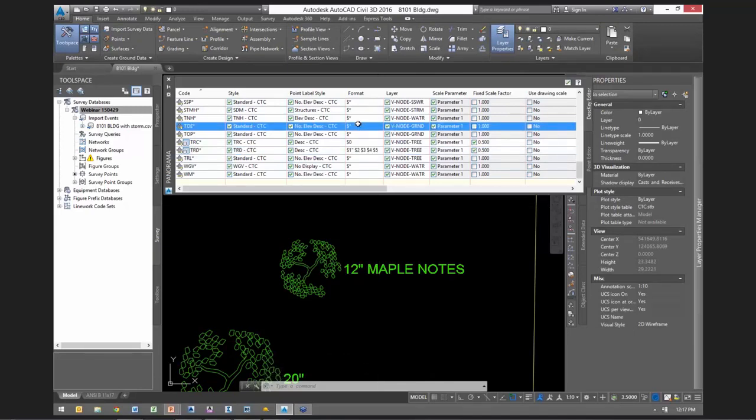What is $asterisk? It means make the full description equal the raw description, meaning there's no translation between raw and full description. That should be your default. That should be what you need for 90% of your shots. It's going to be things like symbols where you have the symbol notating what the object is, what the shot is, and so you don't need to also have the description of it, or you perhaps don't need the full description of it, just a portion of it.